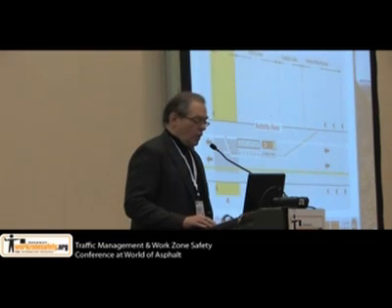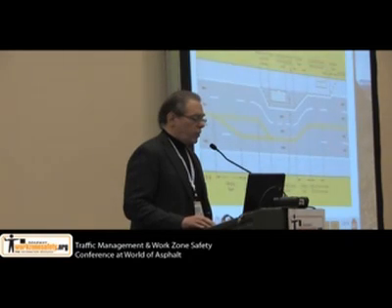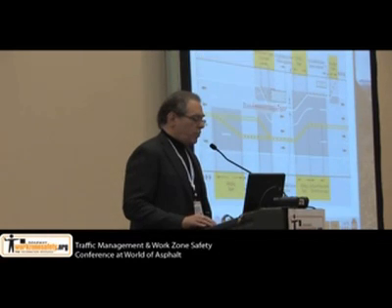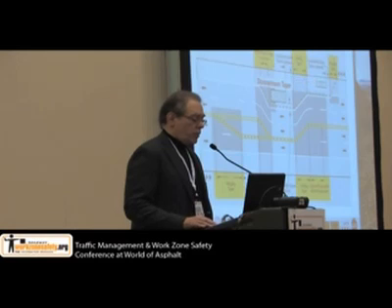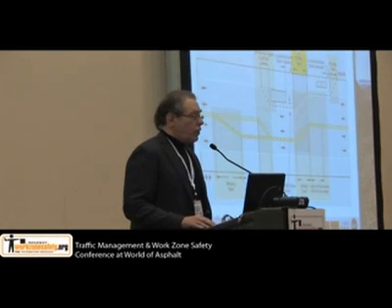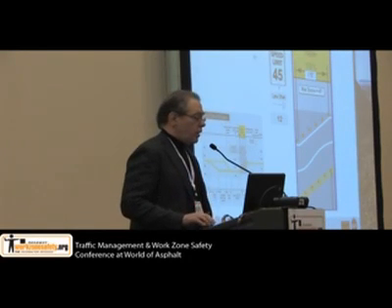Let's take a look at item number 2 over here. What is a taper? And you know, we've been talking about tapers, and this is what tapers are. They're a series of devices placed to move traffic out of its normal pathway. And you can see we have the shoulder tapers, we have shifting tapers, we have downstream tapers, and so on and so forth. And we're not going to look at every one of these here for time, but we are going to look at the shift taper specs as an example.